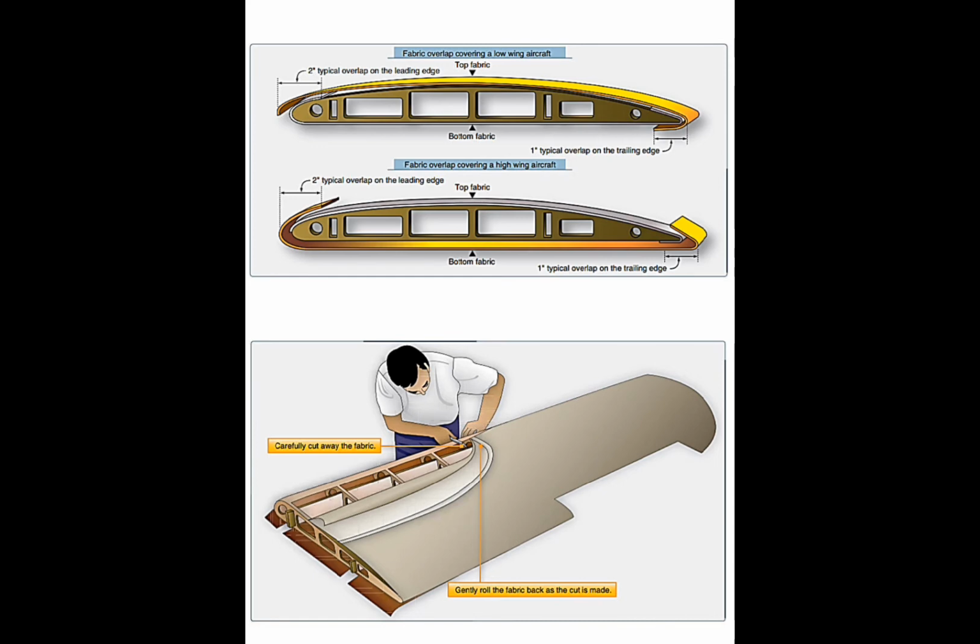Allow the condensed moisture to leave the aircraft as well as furnish ventilation, located on the underside of airfoils. How are drain grommets installed in aircraft fabrics? Directly to the covering. Name the methods of applying fabric to an aircraft wing. Blanket and envelope method.